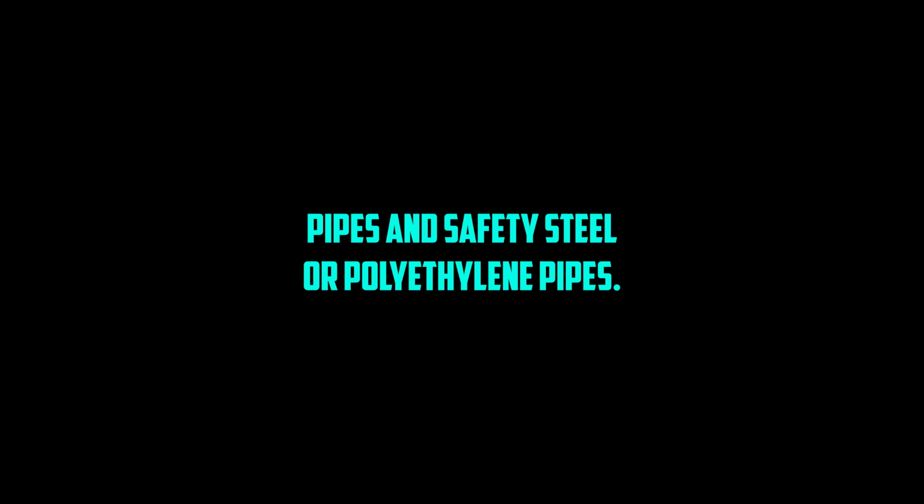Steel or polyethylene pipes. Gas fires, under 60 kilowatt domestic, covered by Building Regs Part J. Need a flue to take combustion products away safely, could be a chimney, special blocks, or a dedicated pipe. Balanced flues draw air from outside and vent outside directly, very common now.